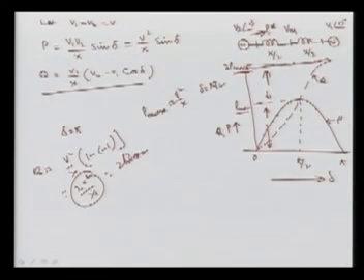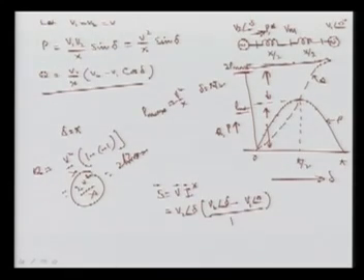Now how did we get it? It's very simple. The power S flowing from here to here, I can write simply as the voltage into the conjugate of the current flowing here. The voltage here is V2 angle delta, these being vectors. The conjugate of I is basically the voltage difference, V2 angle delta minus V1 angle 0, divided by jX, and this is the conjugate.